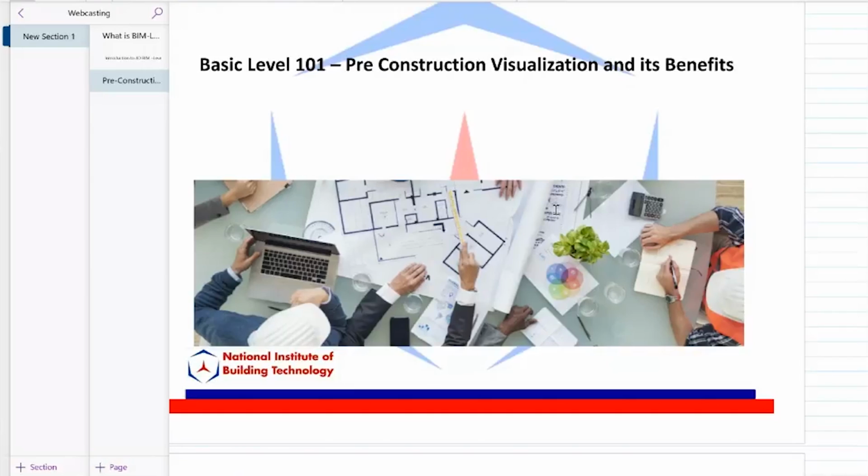So quantity surveying is really critical, right? When you have a BIM model, quantity surveying is a byproduct and not necessarily a loaded job. So when you have quantity surveying information, for example, if you have to find out how much brick masonry you need, how much paint you're supposed to buy, how much concrete is going to be bought, how much rebar you have to buy, those are not things that you do manually with BIM. With BIM, if someone has designed the job, it takes 20 minutes to put out a quantity survey.